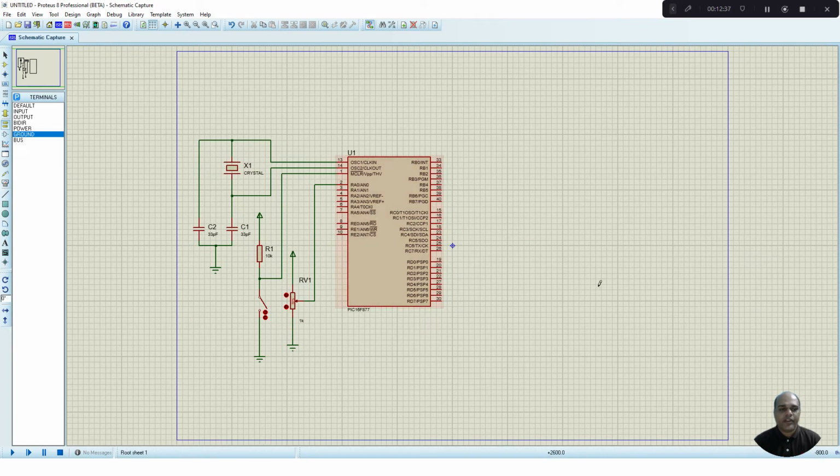Next thing is we need to connect the servo motor. Again go to components mode, PWM servo, place it onto the circuit. Connect the RD0 line to the PWM line. PWM line is the center line of your motor, and the top line is your power supply line.